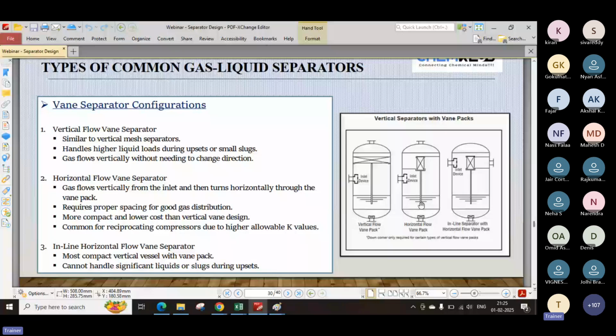This pipe connection, as per Shell, has a minimum 2-inch requirement. However, it is sized using the Froude number, and generally they go for 0.2 to 0.3. But I have never seen any vendor considering the sizing of this using the Froude number, and generally they follow a minimum 2-inch or 3-inch as their company standard.